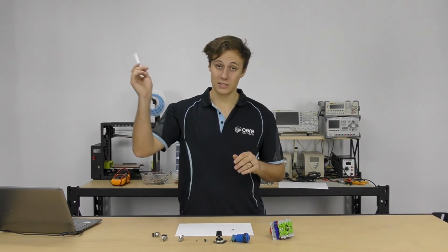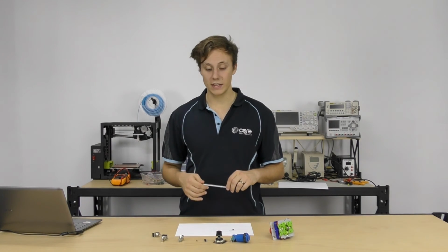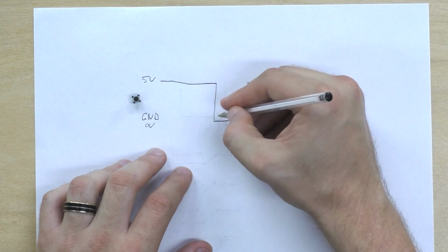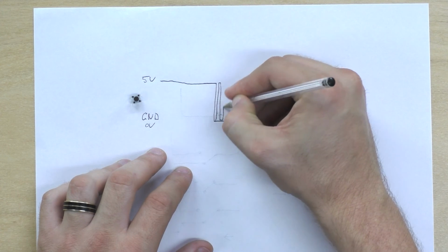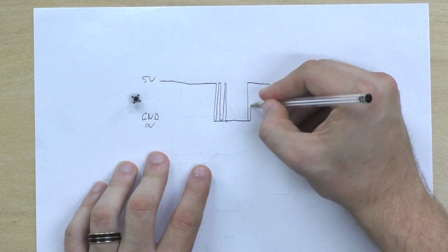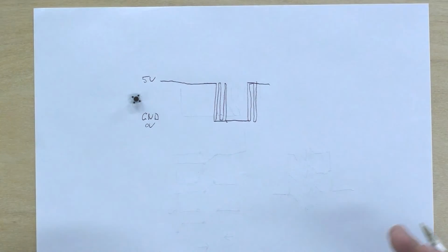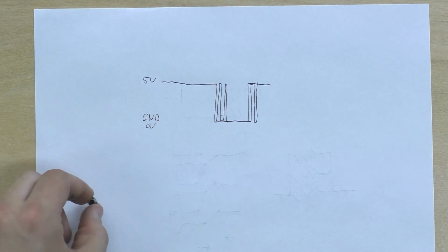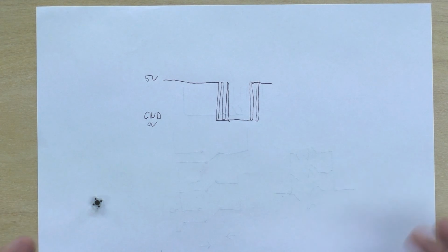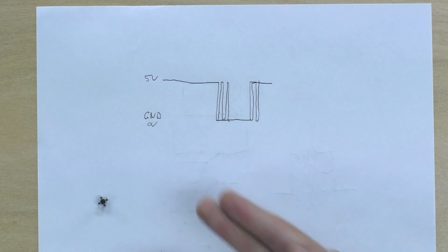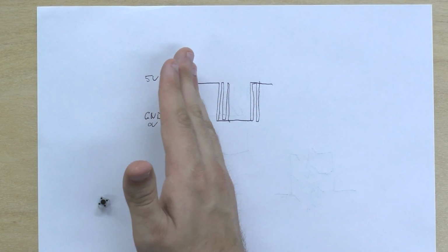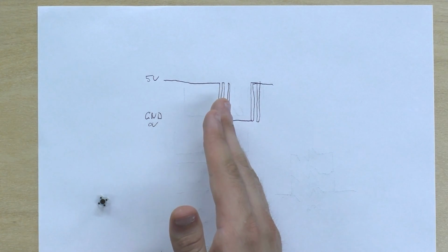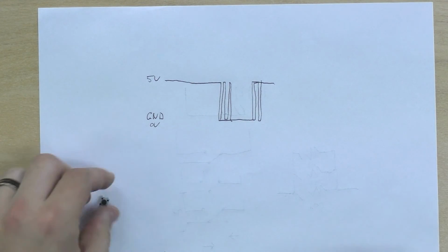microcontrollers operate anywhere between 2 to 4 megahertz, right through to gigahertz. Really high processing speeds. And this is important because if you're sampling the pin, instead of a nice clean break, it'll go down, and then it'll go up, and then it'll go down, and then it'll go up, and then finally it might settle. And likewise, when you release it, there'll be this jitter on either side, and you're going to need to handle that. If you're, say, turning an LED on or off with this switch, you're going to get false positives, and if you're just sampling that straight away, it's going to say you turned it on, then off, then on, then off, and so on and so forth. And that can be a real issue.